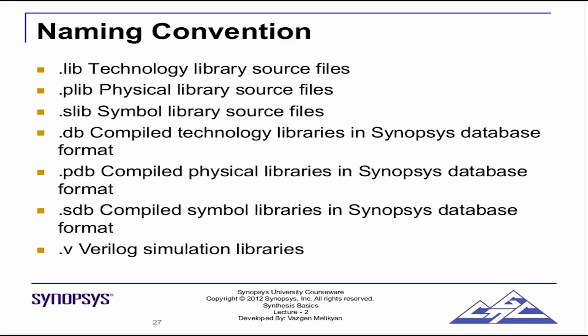DB is nothing but a lib which is compiled. It is a binary format. It is not readable by us. It is compiled by the Synopsys tool, and the Synopsys tool reads it. So wherever you see DB, it is usually the compiled binary format of the corresponding text format. .v is the Verilog simulation library. Now we'll see this in a lot more detail. We'll see an example of this.